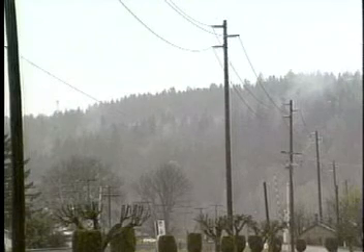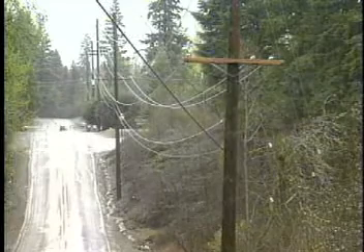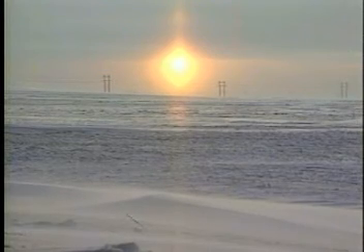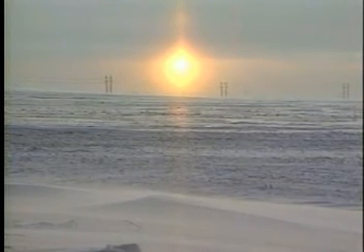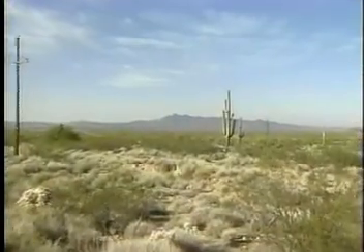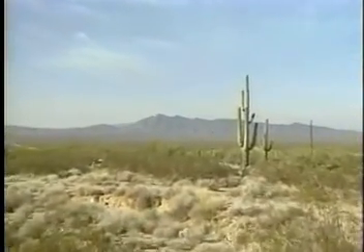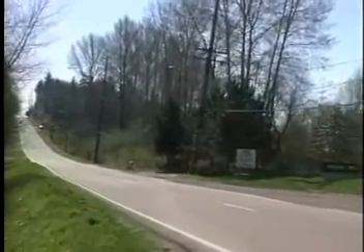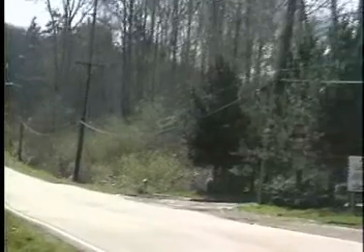The most important concerns with aerial cable placement are span length, cable tension, and cable sag. Cable sag and tension will be determined by the maximum span length and cable type to be used. Sag will also depend on the minimum required ground clearance at the center of the span. This must also take into account the effects of wind and ice loading throughout the year, as well as cable expansion and contraction with ambient temperature changes. Keep in mind that sag and tension are inversely proportional. The more tension, the less sag.